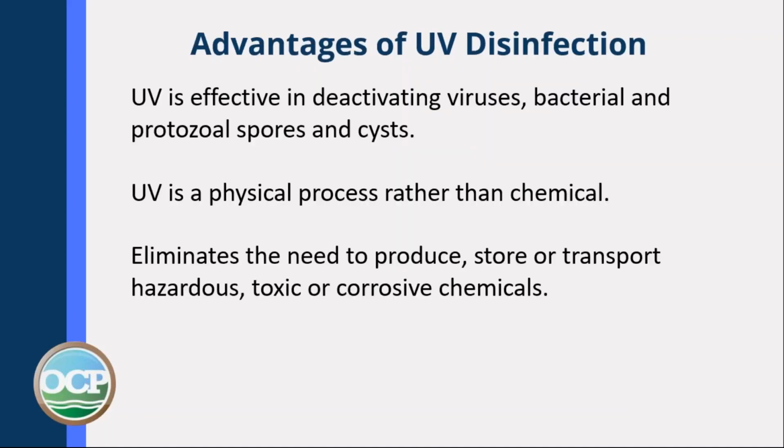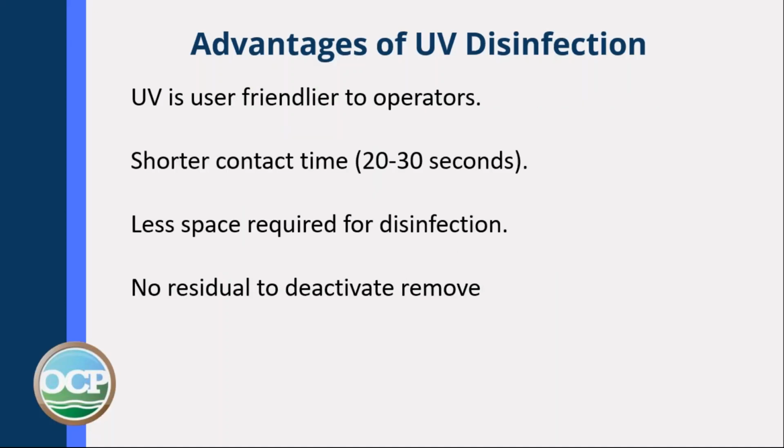The advantages of UV. UV is effective in deactivating viruses, bacterial and protozoal spores and cysts. UV is a physical property rather than a chemical property. It eliminates the need to produce, store, or transport hazardous, toxic, or corrosive materials. UV is user-friendlier to operators.